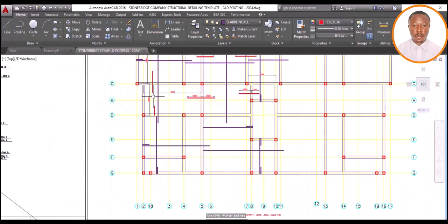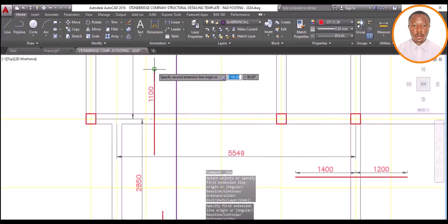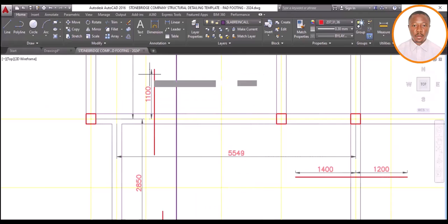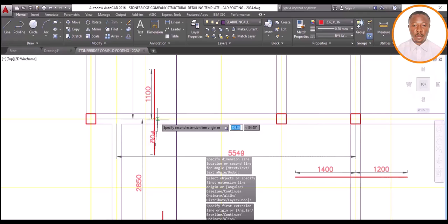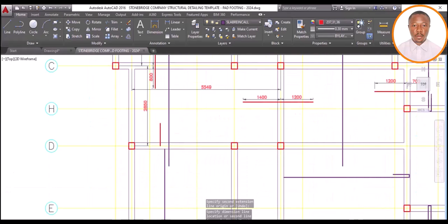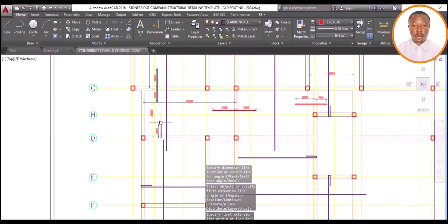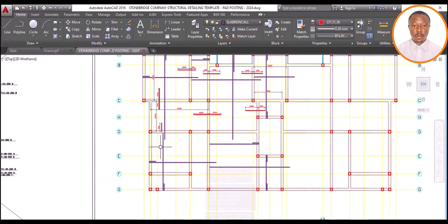So now we need to tell the engineer at site the length of our top reinforcement into each slab: 1,100. Okay, good. And from this slab to this, we say 800. And from here also into this slab, 800. You know why it is 800? Because it's the same slab. This is a panel, isn't it? Into this one, this becomes my top reinforcement.